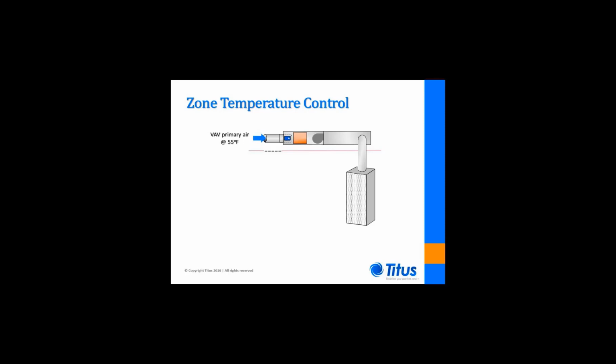Conventional 55-degree supply air is delivered to a series fan terminal and then mixed with return air from the ceiling plenum to establish a constant volume, variable temperature delivery of air to the space. This is, however, not advisable, as recirculation of return air will just short-circuit the contaminants back into the space itself.